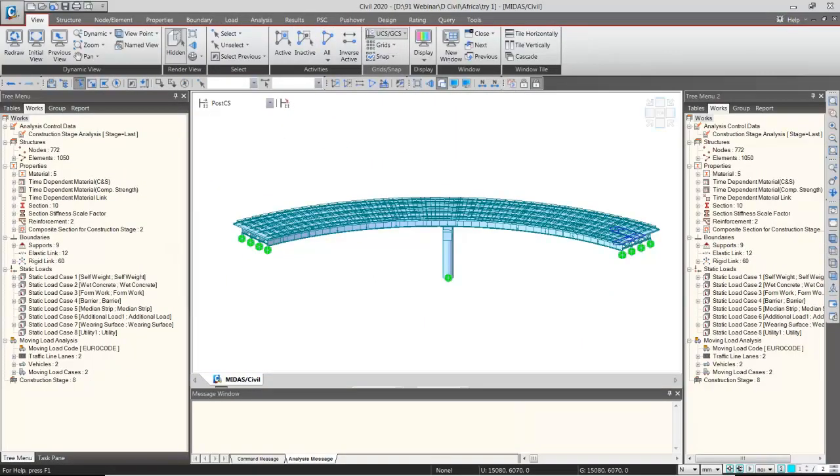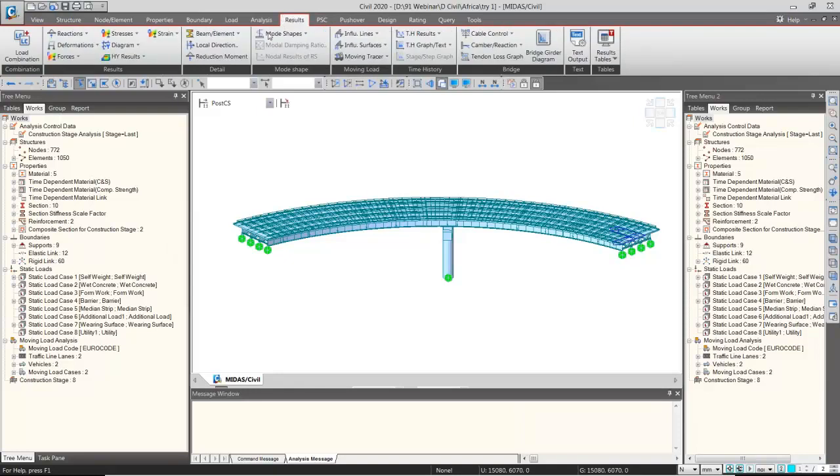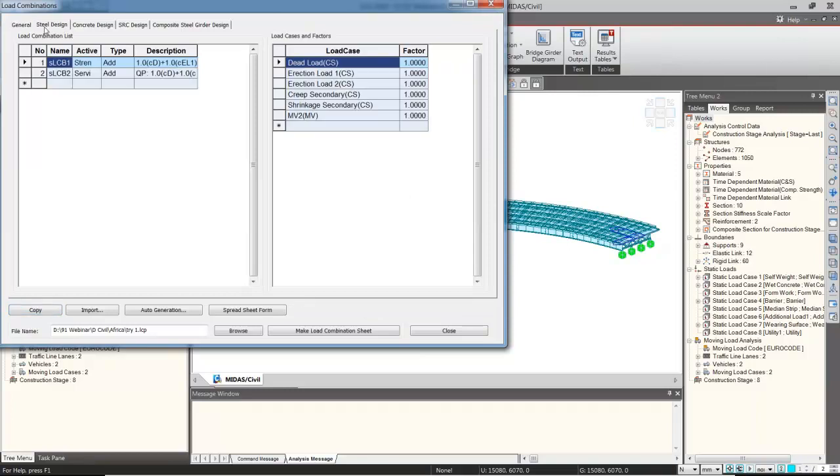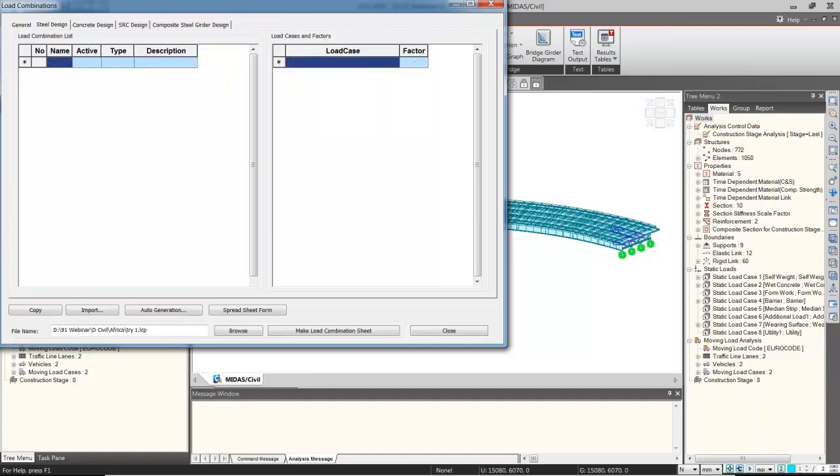Okay, now let's look at the analyzed results over here. In the results part, I would like to start again from left to right. That's the work procedure. So we start with the load combinations. Now the load combinations are required in the steel design so that the design will take place as per the given load combinations. These load combinations can be automatically generated. Because this is already created, I'll just simply select and delete them. Okay, and I'll do it in front of you for a demonstration.